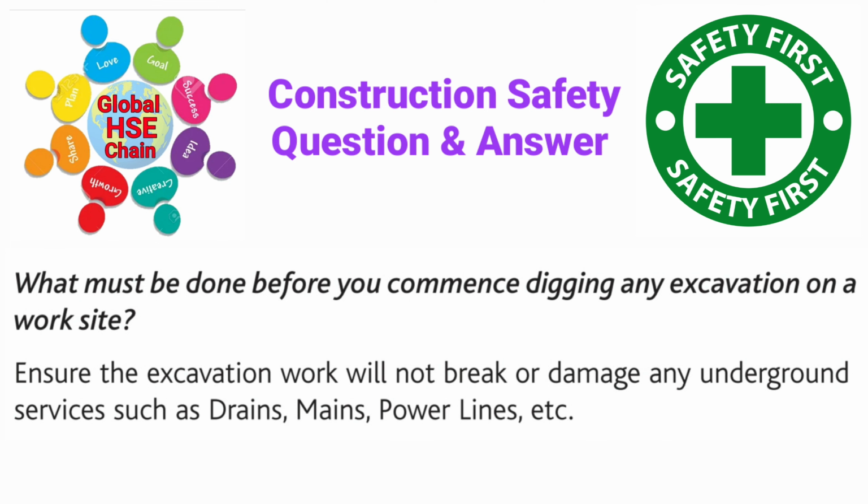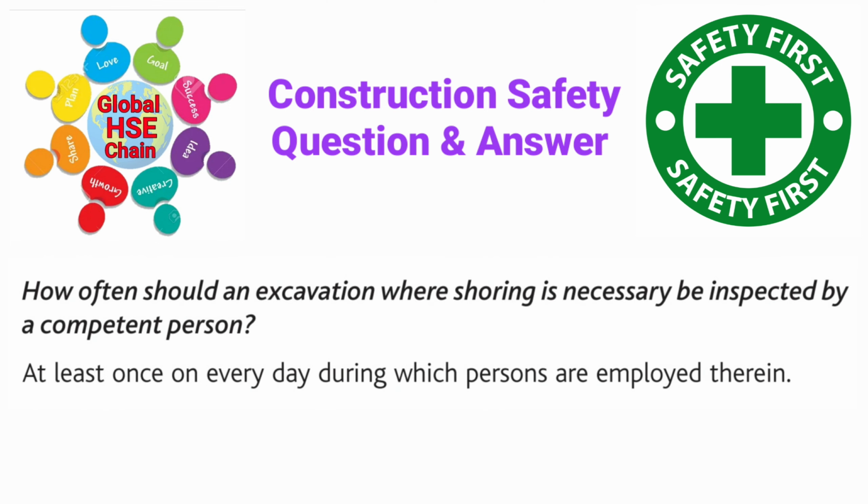Question is, how often should an excavation where shoring is necessary be inspected by a competent person? The answer is at least once on every day during which persons are employed therein.